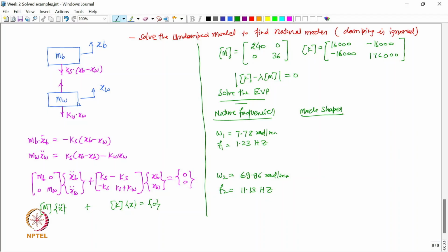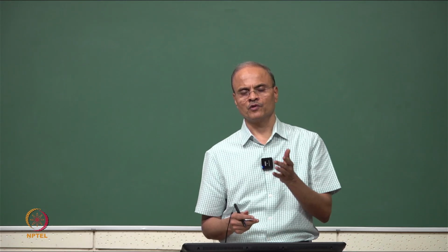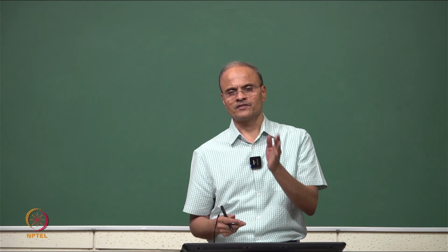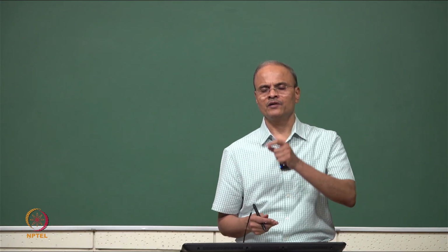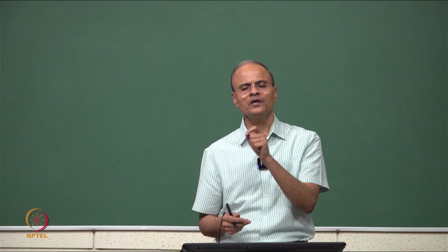And then if you look at the mode shapes, that is nothing but eigenvectors, right. Those mode shapes, and if you mass normalize them, so I also in fact mass normalized them. Mass normalized eigenvectors means, we studied in the lecture classes that when we take psi transpose m psi, that basically gives you the modal masses, and then you divide each eigenvector by the square root of the corresponding modal mass, then you get the mass normalized eigenvector.